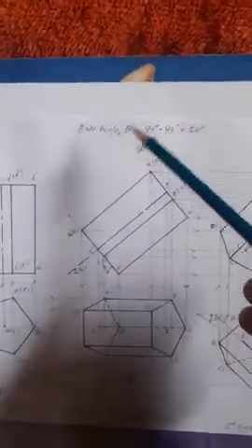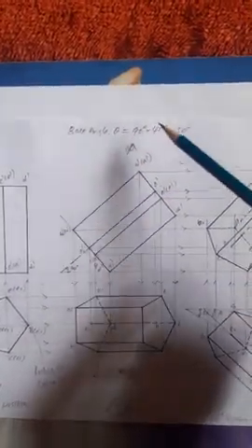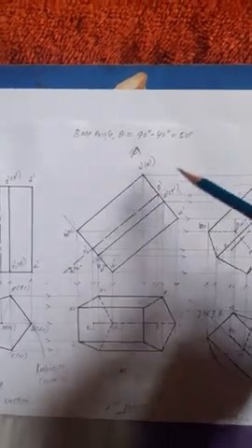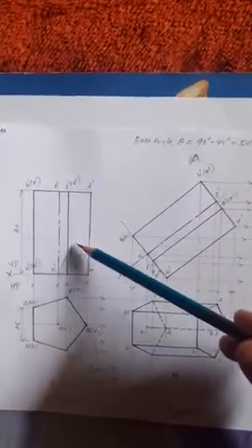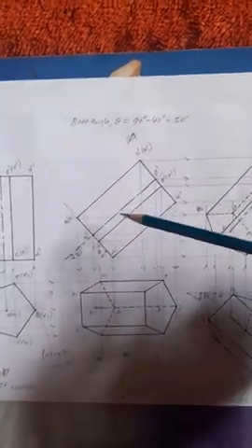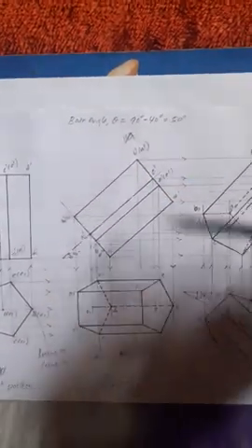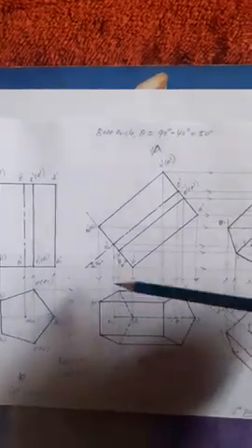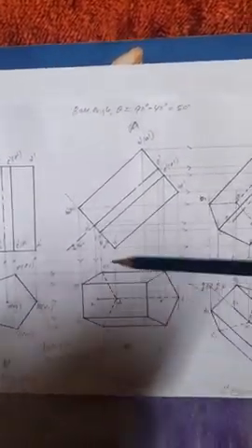That is 40 degree. The base angle theta is equal to 90 minus 40, that is 50 degree. Now just replace this first position, front view, on the 40 degree line. That is the second position, front view, over. Then project it, all vertical projectors and horizontal projectors, will get the second position, top view.